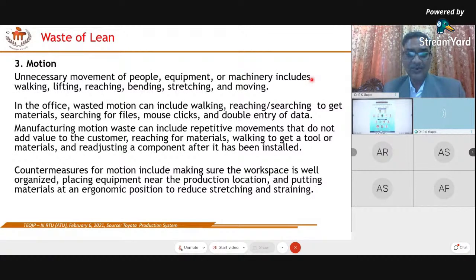So that is to be identified. That's why we have mentioned it as the most frequent defect to be identified, and then remove that. The process should be designed so that it detects abnormalities and does not pass any defective item along the production process. And then redesign the process so that it does not lead to the defect. And use standardized work to ensure a consistent manufacturing process, that is the defect.